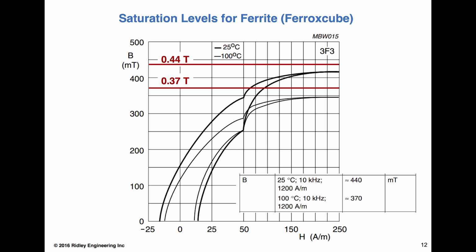The more interesting part is, when you run at short duty cycles, how does that change? I did an article on that recently, and lots of other research has addressed that when you get down to quite narrow duty cycles, you are going to see the loss climbing. But I don't think this is something we can expect the core manufacturers to deal with. If they give us just the sinusoidal, we've got lots of different ways of using that data to project what the short duty cycle non-sinusoidal is going to be. And I think it's accurate enough, quite honestly.